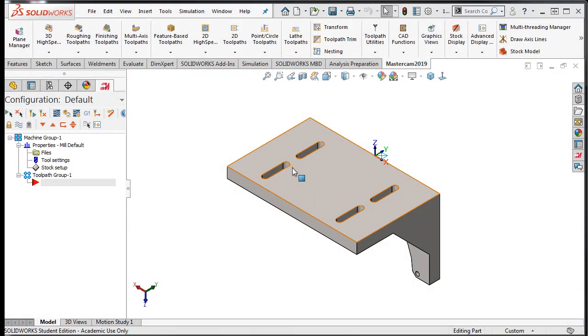Machining slots is a common practice, and there is a toolpath dedicated to making this an efficient task. In order to do so, I have to set the proper cut parameters and calculate the appropriate tool size for this part. I have 4 slots, so I'll set the toolpath up for one of them, and when I'm happy with the toolpath, I'll add the other 3 slots geometry.